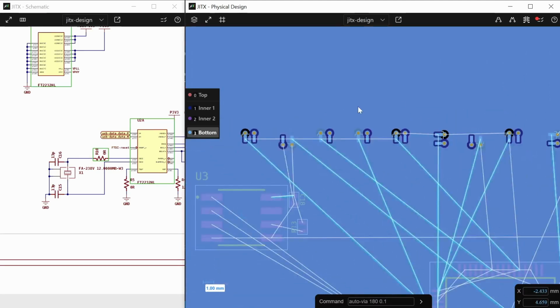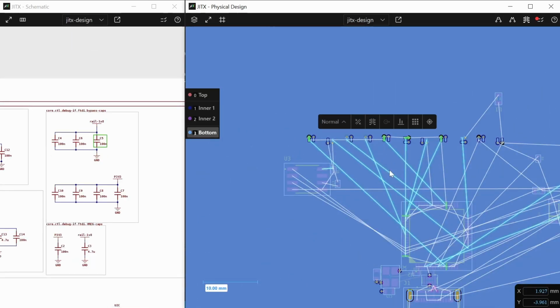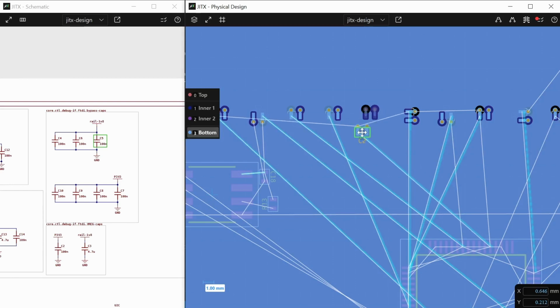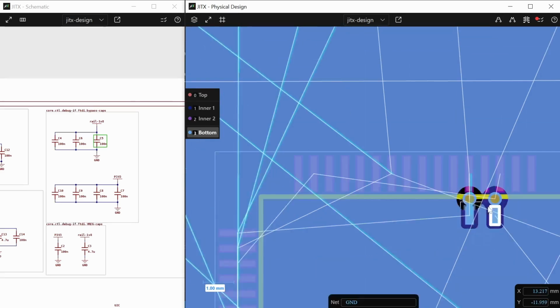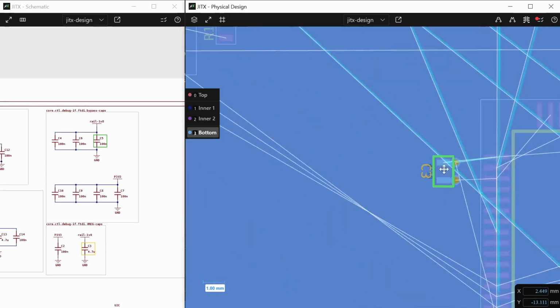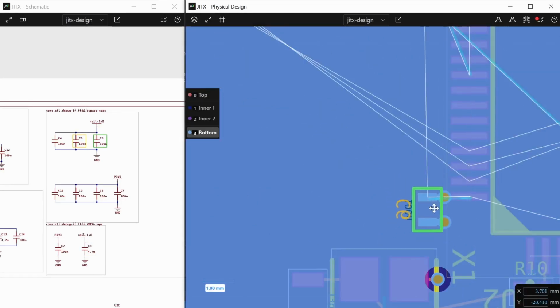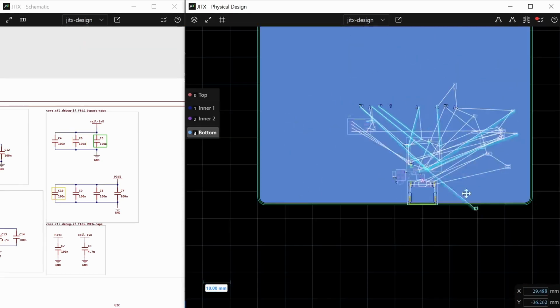And we now have some capacitors that are ready for placement. Again, we can use a short trace to guide our placement. So if I exit this, pressing A on this net, you can see that there are multiple capacitors bypassing this net, bypassing each of the pads on this 1.8 volt power net. So these turquoise lines indicate which pad these capacitors go with, because we know more than just naive information about our design. Rather, we know exactly, with the short trace annotation, which capacitor that's meant to bypass. So we can just easily move these capacitors into place by following the guidance from the short trace. And this is very helpful as you start scaling up from one set of capacitors to several tens or hundreds of capacitors.